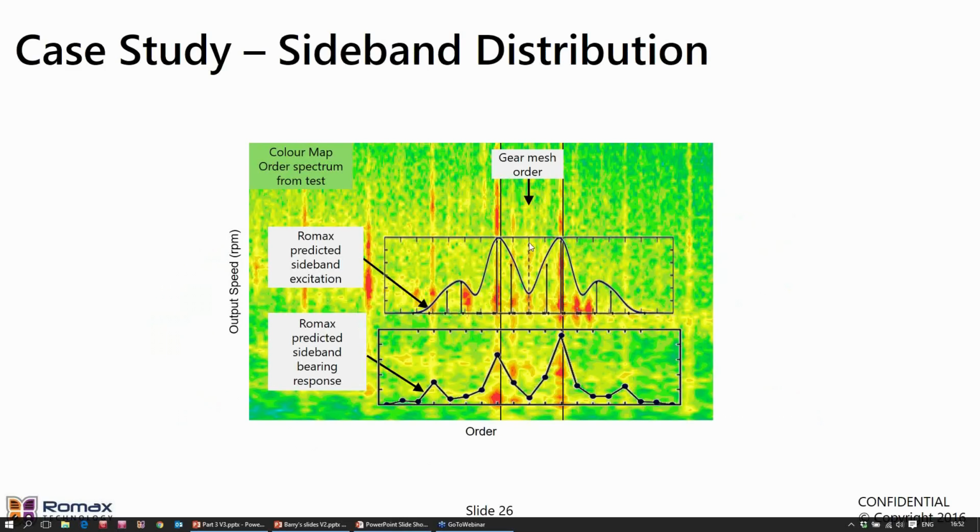at the mesh frequency. There is hardly any here at all. It's all been moved to various sidebands by a mixture of type 3 and type 1, but the overall energy contribution, the overall sideband behavior here is coming predominantly from the type 1 sidebands.